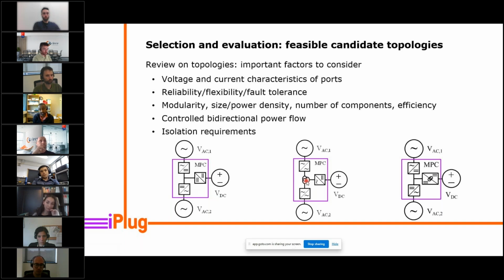So we use that as part of the module. And the last one is to use the best knowledge, the experience, the reliability of the technology on the back-to-back using half bridges, but converting them into full bridge cells to take advantage of the flexibility we can get in the voltage level we generate on the AC side and on the DC side, which would be different. We can go to a lower DC voltage level, where interfacing a low voltage DC would be much, much easier.